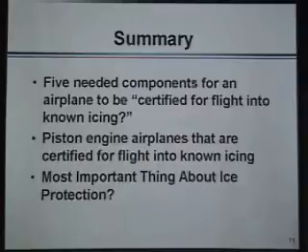Now, this last question: what's the most important thing about ice protection? Well, it's not that I want to say don't read the approved flight manual, because that's certainly important. You're going to need to know how to operate everything. But I submit, and of course I'm grading the test, that even more important than reading the approved flight manual is talking to a pilot who has flown that make and model of airplane before in actual icing conditions, and asking, hey, how thick does that ice need to get on the wing before I turn on the pneumatic boots? Hey, does that pitot-static heat really work well if it's really heavy icing? Hey, how does that alcohol prop thing work out? Does it really keep the ice off of the propellers, or does it not work that great? Am I going to be unhappy about it?